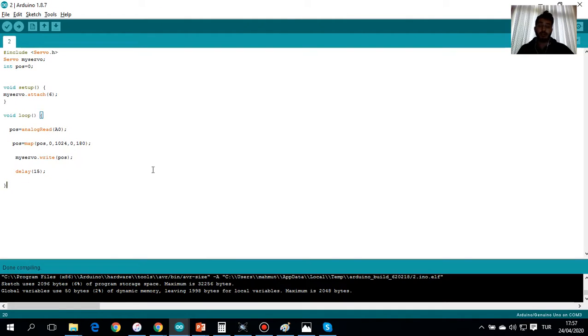What kind of program do we have to run? This is an easy project that I'm going to add in the description so you can have that specific code, but you can also adjust the code according to your own project details. The first thing to know is that we are going to add the servo motor library with the code, including Servo.h, and then I'm going to have a variable called myservo, and the data type is going to be Servo, just like we learned about data types.